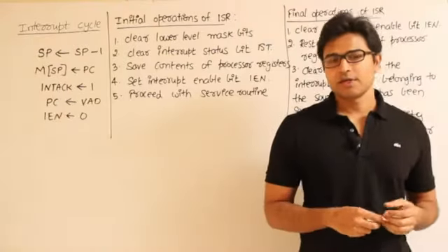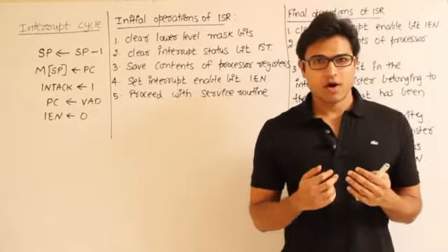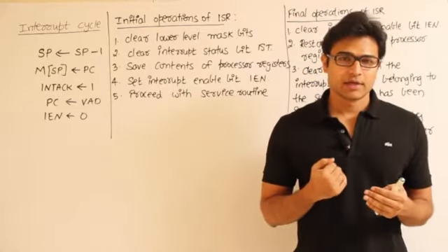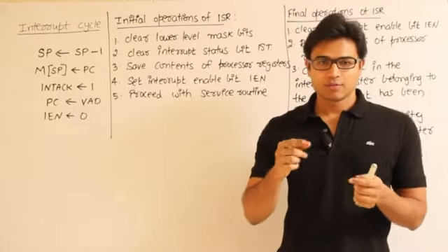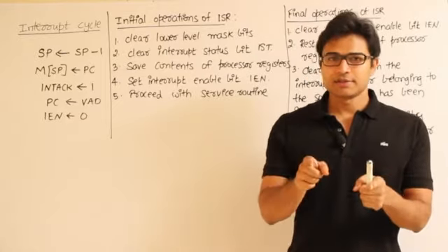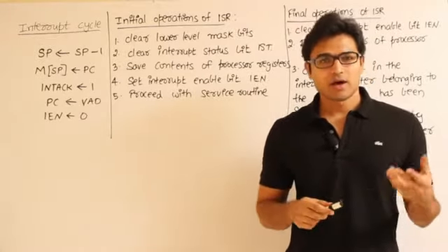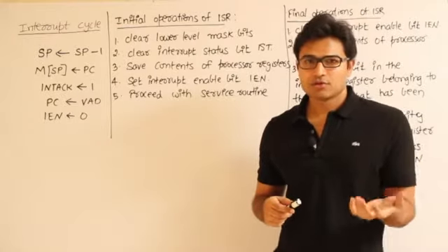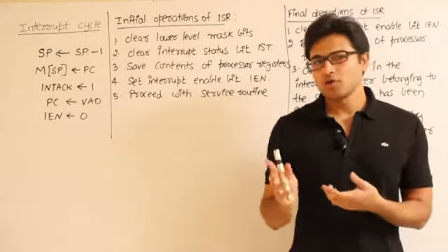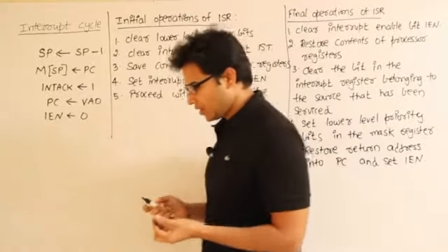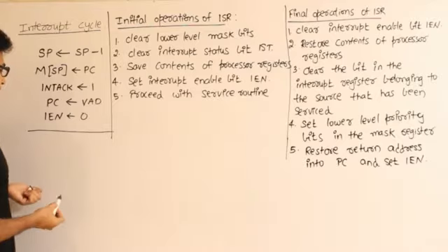The main thing required by any IO device is either it is trying to provide you some input or it is asking you for some output. In case it is trying to provide you some input, then it is putting that input in a register and you have to read it into your registers, right? So the heart of the problem is you have to solve this problem by executing either INP or OUT like this. We have already seen these two instructions when we were discussing the design.